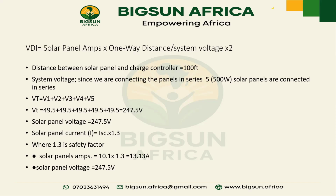If your panels are in series, then you are going to have total voltage, that is VT. It's going to be V1 plus V2 plus V3 plus V4 plus V5, which means it's 49.5 in 5 places.